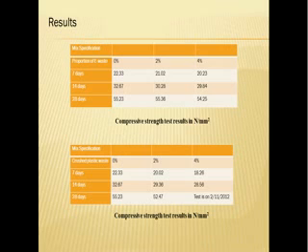The result for the first, the proportion of e-waste, as predicted: the compressive strength falls down. This was because the ground electronic waste is not a cementitious material, so it does not bind with cement. Mixing it in a higher proportion reduces the packing density and thus the compressive strength.